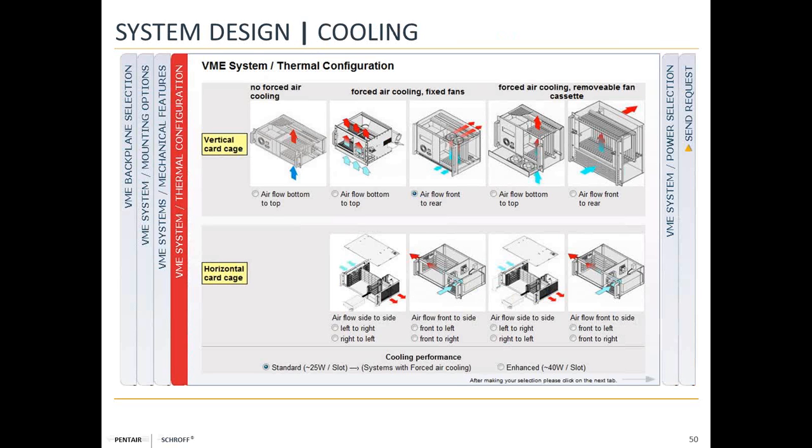Also critically important is the direction of the airflow when cooling blades. So Schroff offers top to bottom, front to rear, left to right, right to left, front to left, and front to right. So many, many different options in terms of the direction of the airflow. And once again, our team is experts on this type of thing with the cooling, so they will find the optimal solution for any specific design or application.